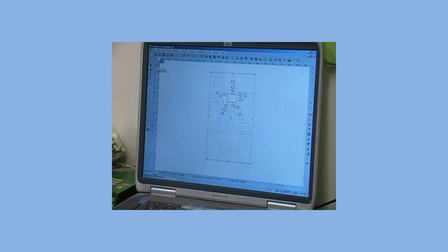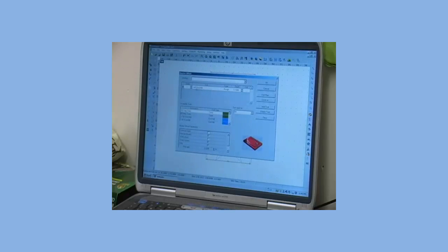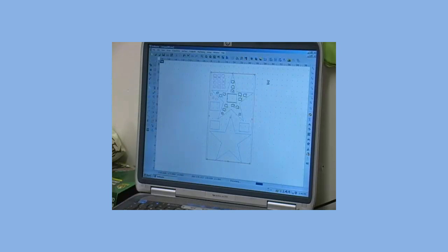Go to your Routing Offset tool. 1/4 inch end mill is already selected. Now click external male. Leave inlay selected and hit OK. Once again, you'll see it processing. If you do not see that, it's not creating a toolpath. You should get some green circles and blue arrows all around.